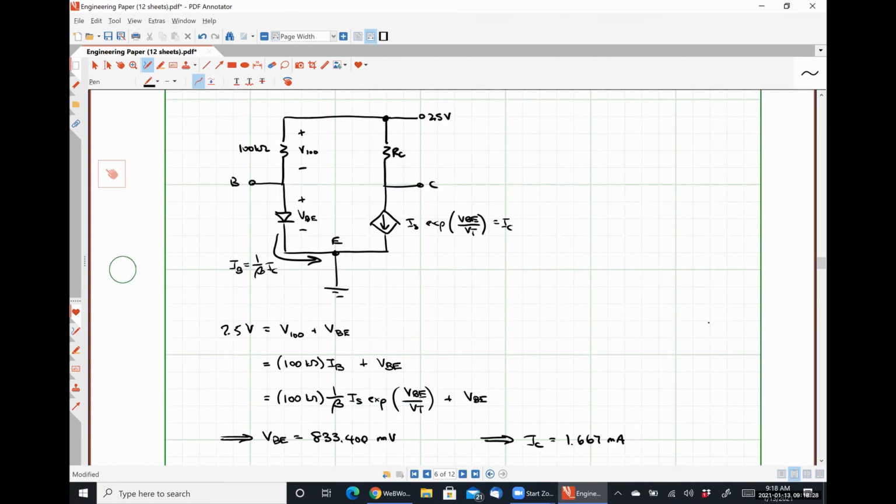So how would we go from here to determining the resistor value that forces VBC to be 200 millivolts? Because we know that anything larger than that value will make VBC greater than that, right? So I'm going to say that VBC, plus here, minus here, is 200 millivolts.